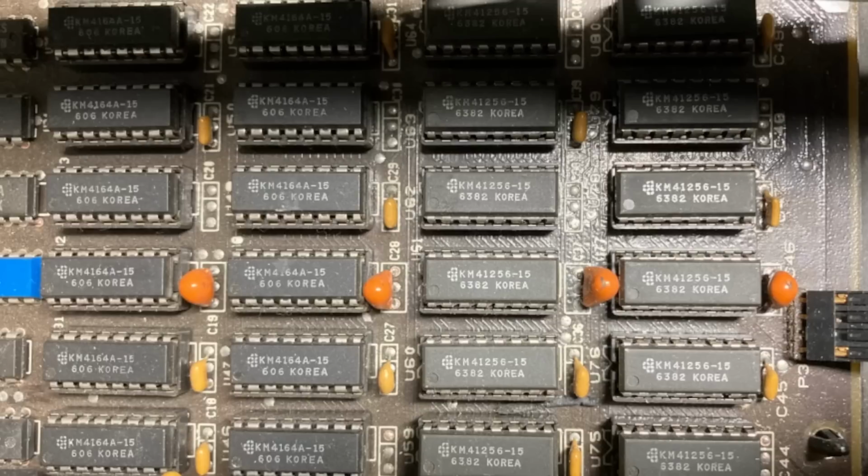It turns out that on the XT, there are only two kinds of chips that are pretty common. There's the 4164 chips, which are 64 kilobits each, and the 41256 chips, which are 256 kilobits each. And they're arranged in banks of 8, so this will be a 64 kilobyte bank, and so will this. And then we've got a couple of 256K banks. And basically, all I need to do is make sure that I'm energizing all the rows of each bank.